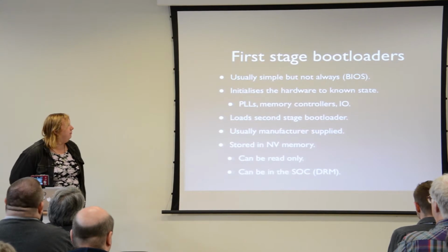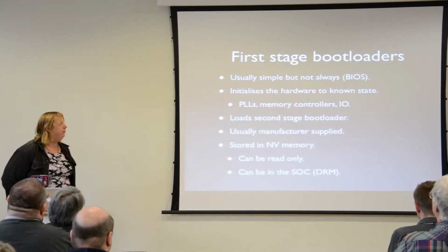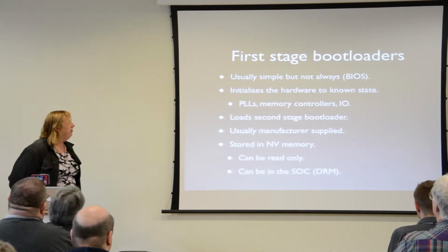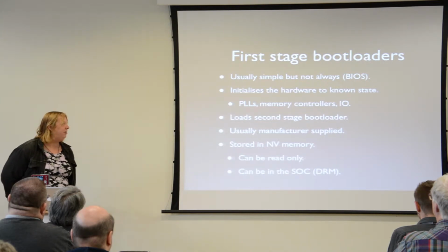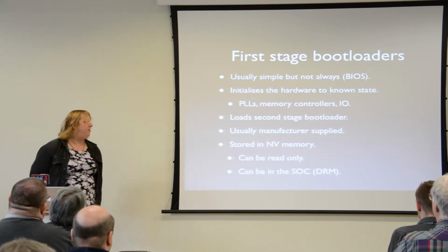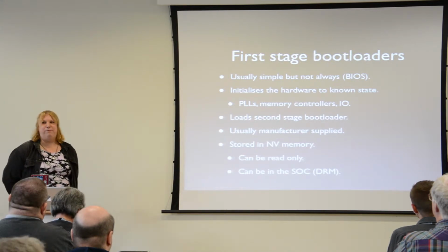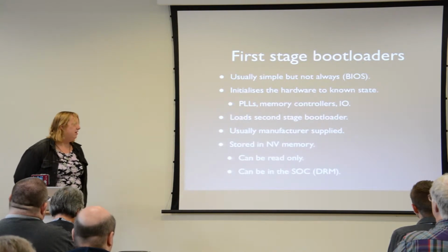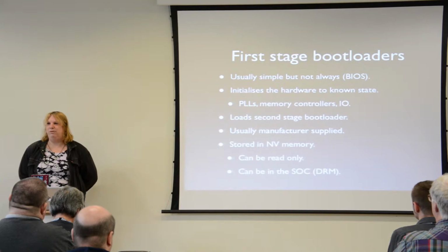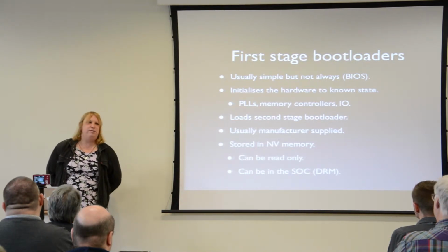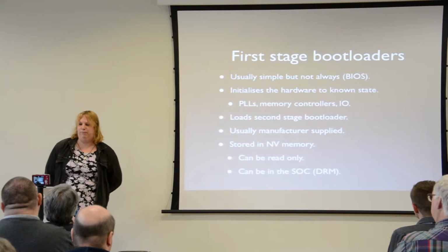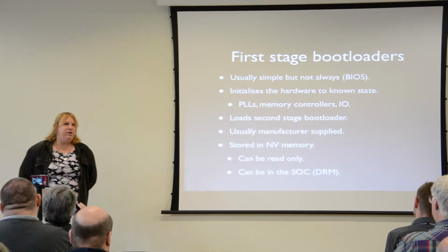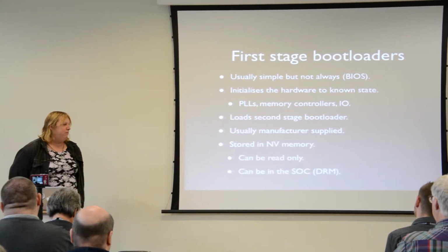First stage bootloaders are usually pretty simple, but technically the BIOS in a PC is a first stage bootloader, and that's not very simple. It initializes the hardware to a known state. It's basically there to get the second stage bootloader going. Usually it's from the manufacturer, because it's pretty hardware specific, and stored in non-volatile memory. So quite often in modern chips, there's a bit of ROM or programmable memory in the chip, and once it's programmed, it's programmed. So we go back to these system on chips and so on.